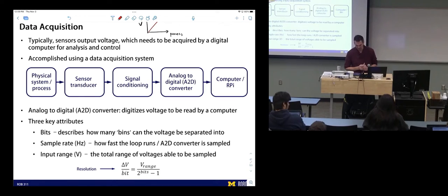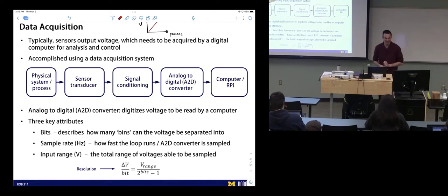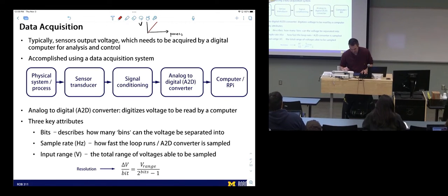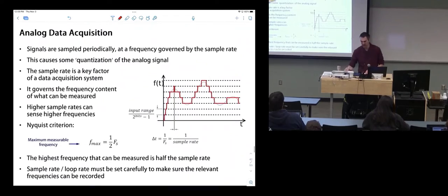If you were out of range for a physical sensor, what would happen to it? If your voltage was too high, or you went outside the calibration regime of the sensor, would it give you random values, or break the sensor? Usually it would continue to work, become nonlinear, and eventually destroy the sensor. They can usually go some amount overhead, but eventually that will destroy the sensor. Okay, good. This is important stuff.